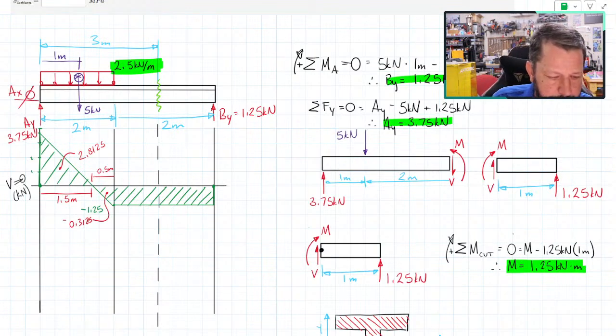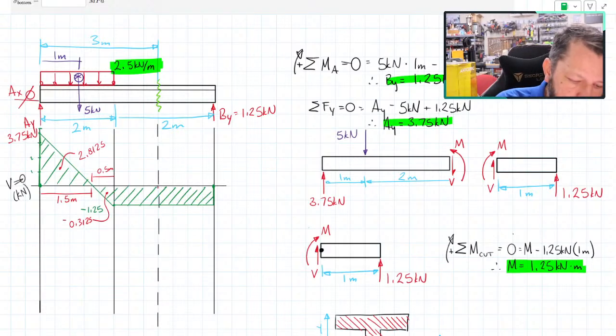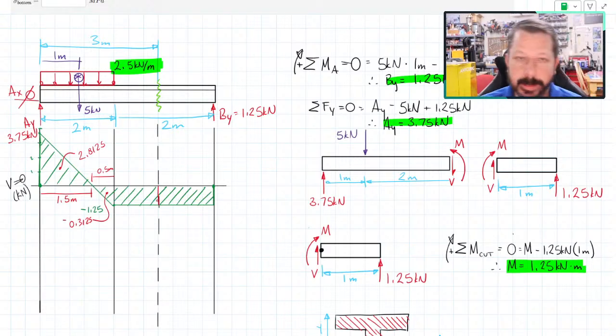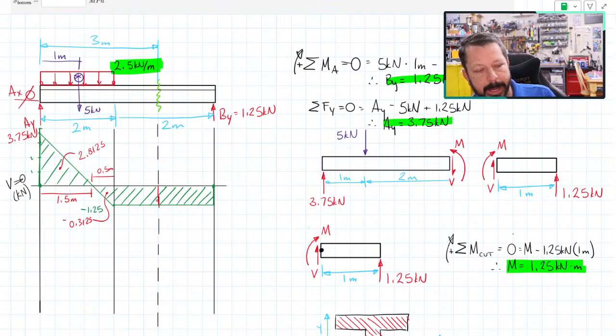This rectangle, I believe I will divide into 2. Normally you would not do this part, but I actually want to know the height at that section line that I drew, the dotted line. So that's why I'm going to treat this as 2 separate triangles, just so I get that height in my moment diagram directly without having to figure it out.